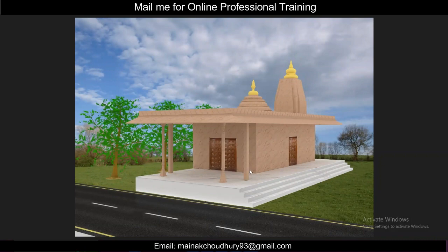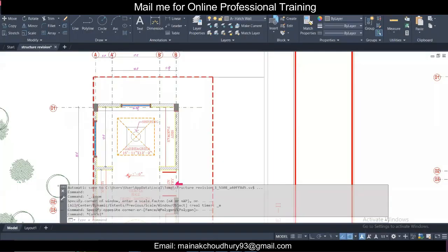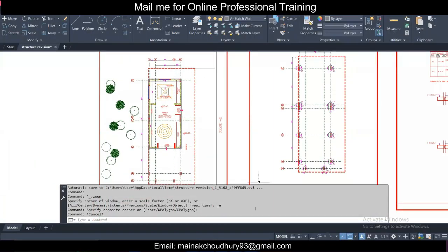And the person who is constructing has taken it up from this plinth level. So the column was already there, the foundation was already there, so we don't have a say in that. The column will be the same, plinth beam is already done. Now the columns are going up. But we have a say in the roof beams. So mainly we have to check the roof beam sizes. Okay, and we can also give the slab reinforcement details and also the roof beam sizes. So these two things mainly we have to check here. And as is, we have to limit ourselves to the data which is available here.